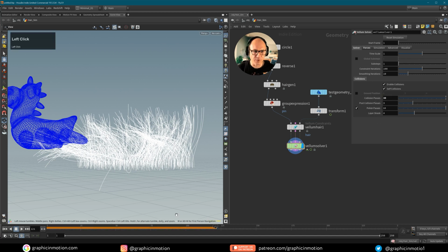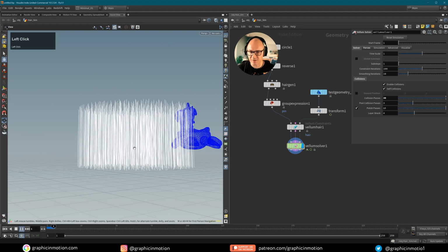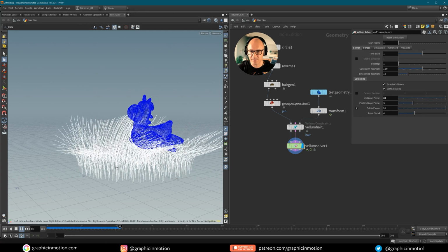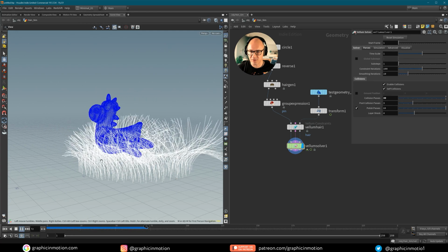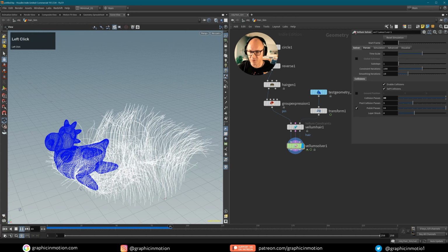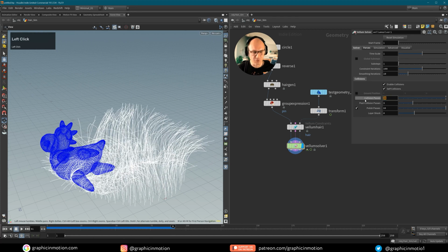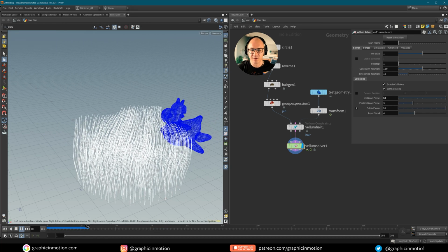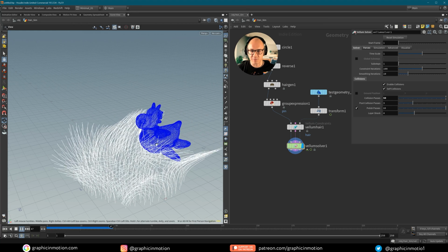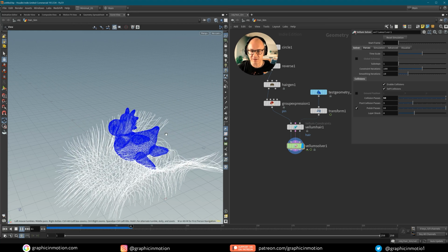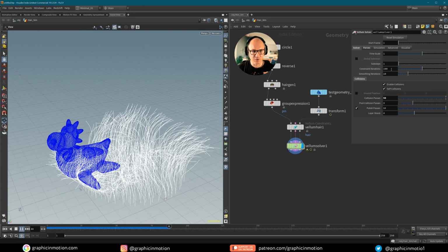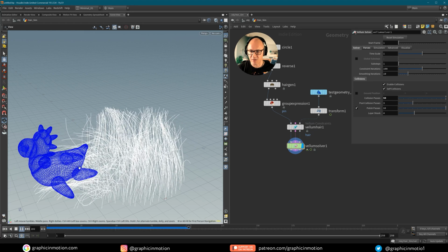You can set them to 30. This will probably not be enough in our case. Let's take a look. Sometimes this is already enough. And I'm not sure. Let's see. No, you see some of them are still intersecting, so you can increase this slightly to 50, maybe to 100. The collision passes will make a simulation also slower, but not that bad as substeps. And the advantage is that it does not really change the behavior of the constraints. And if you add more substeps, you add more constraints, and usually the behavior will change a little bit.